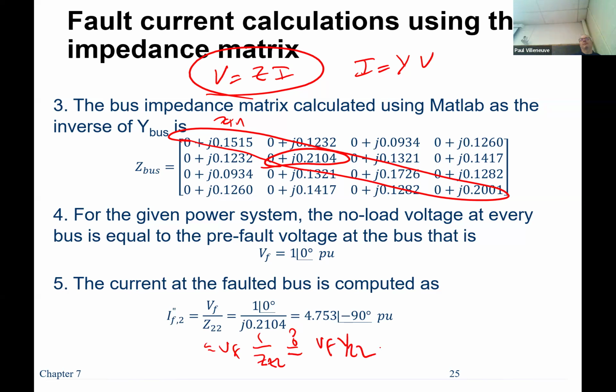Yes. No. Why not? Are you telling me? Now I've got to really pick on you guys. So if Y bus here is equal to Y22, do you mean Z bus, which I get from inverting Y bus, raised to the -1? Do you think Z22 is really just going to be Y22? Not when you invert the matrix, unless it's a purely diagonal matrix, with only diagonals and everything else a 0. When you invert a matrix, the terms aren't 1 over, right?